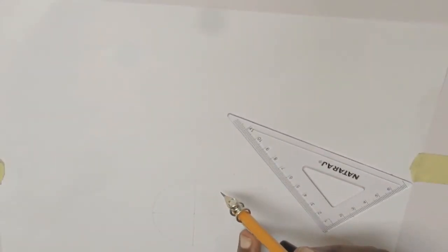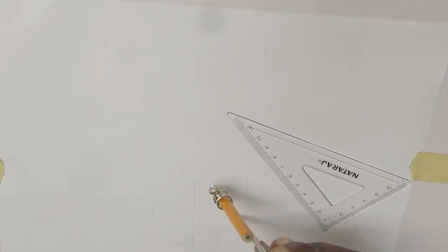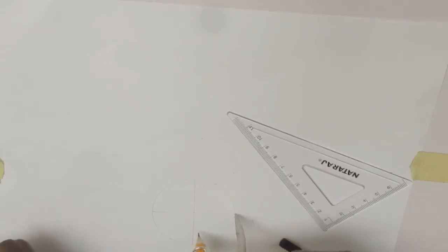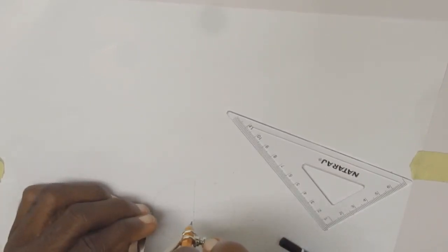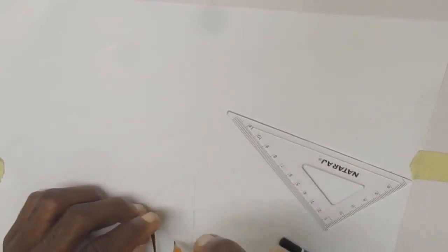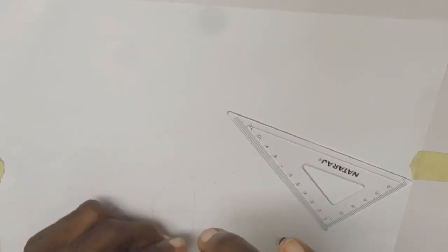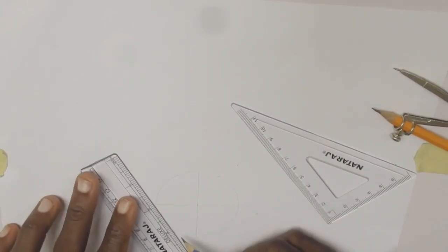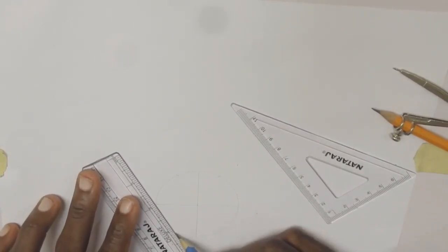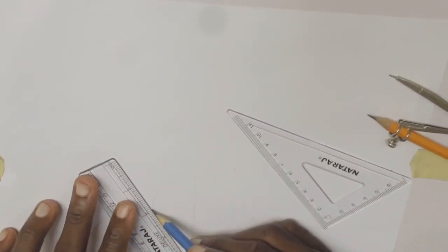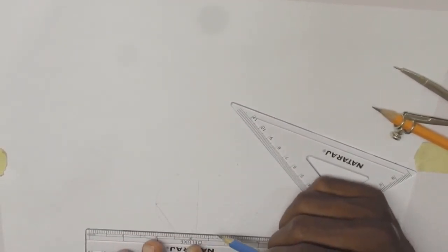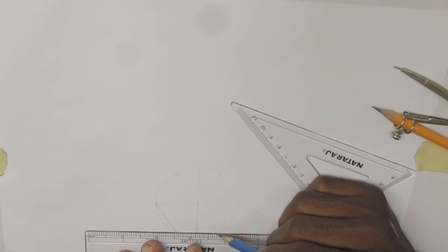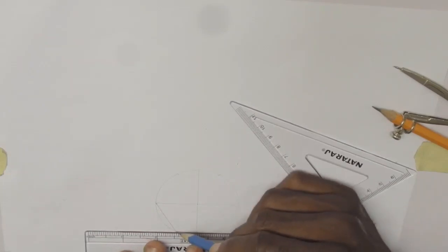And then when we draw the circle, we put in the center lines. Then with the same radius 30, from that point you mark twice up and down, and at the other side too you mark with radius 30. These points that we have marked will be part of the vertices of the hexagon. So we draw straight lines to connect them like this.